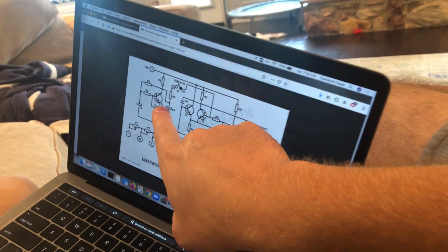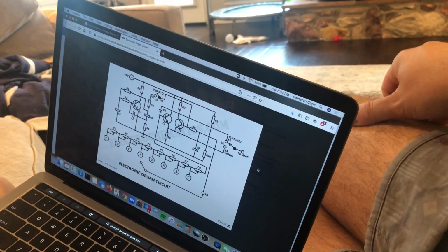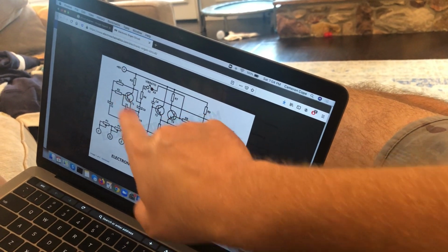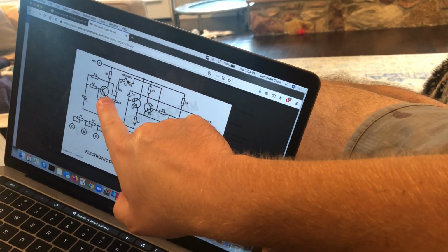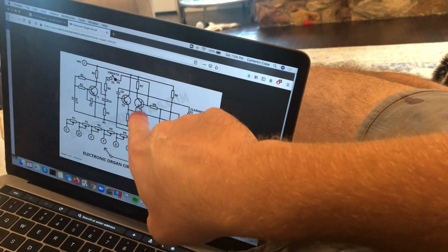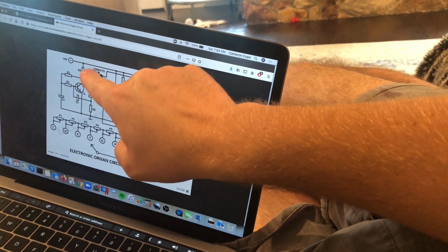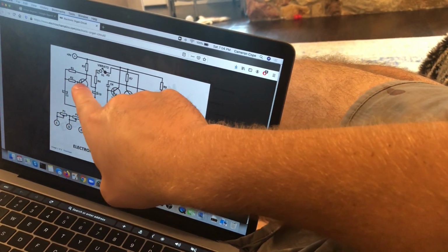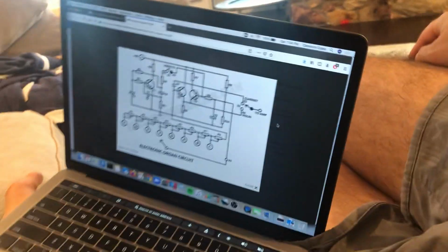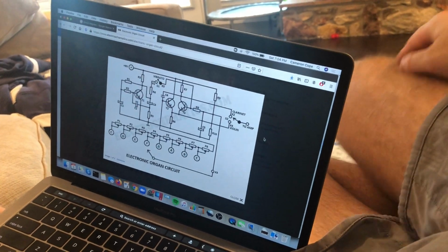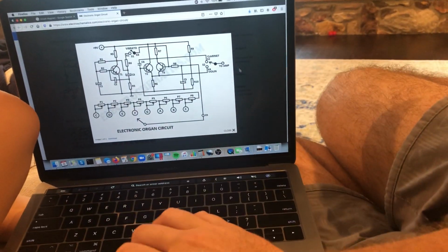What is it? I know it's confusing. It's confusing because on your snap circuits, T1 is a transformer. Right. So that's why you're thinking it's a transformer. But the symbol itself, like we were talking about earlier, is a transistor symbol. So on this circuit diagram, T1, T2, and T3, see how they're all the same? Those are all transistors. So when electricity comes in, electricity has to also come in here to let the electricity keep going where that arrow is. That's what a transistor does. It has a voltage gate that controls the flow of the electricity. So it's kind of like a switch that you don't push; you control it with voltage.